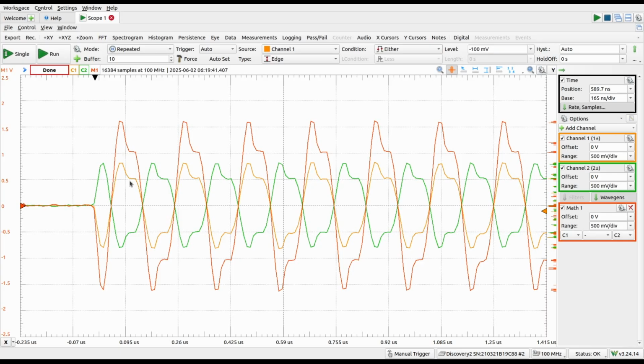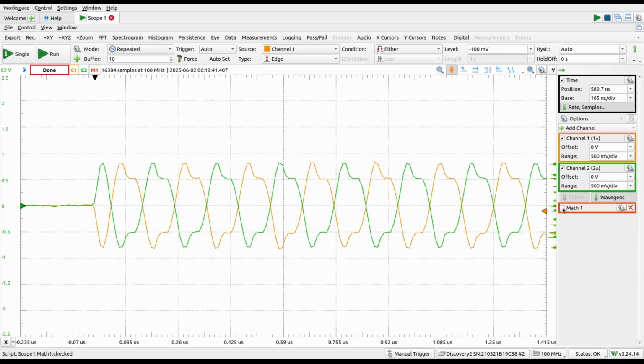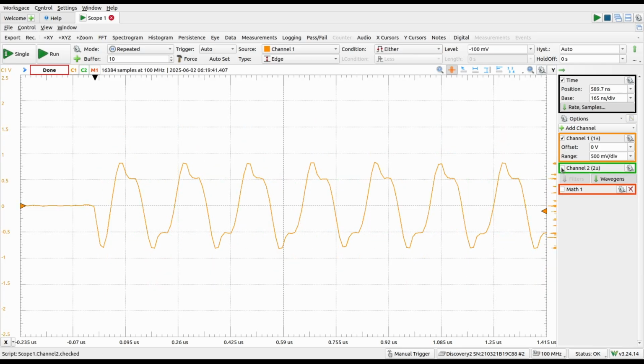The purpose is this: if you have, let's say, an impulse distortion on the cable, say the cable goes close to a vacuum cleaner or electrical engine, and the signal is impacted by the electromagnetic impulse, then both differential signals are impacted, and the differential result will still be the same.